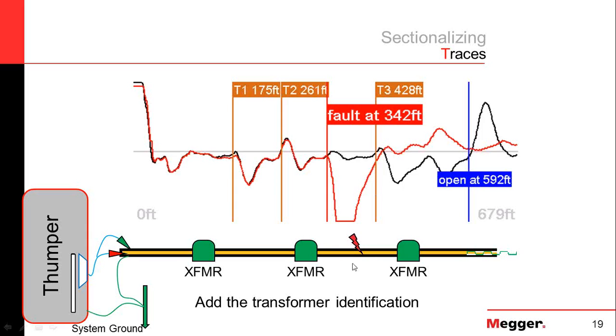He would go down to this transformer 2 and 3, isolate this cable, verify that it's faulted, and if he verified that he found a bad spot, then he can quickly loop around and restore power. And then it's probably the middle of the night and rain, and he's going home. Later, someone will come back on this isolated cable and do a precise fault locate and either repair that cable if it's direct buried, or perhaps pull and replace it if it's in a conduit.